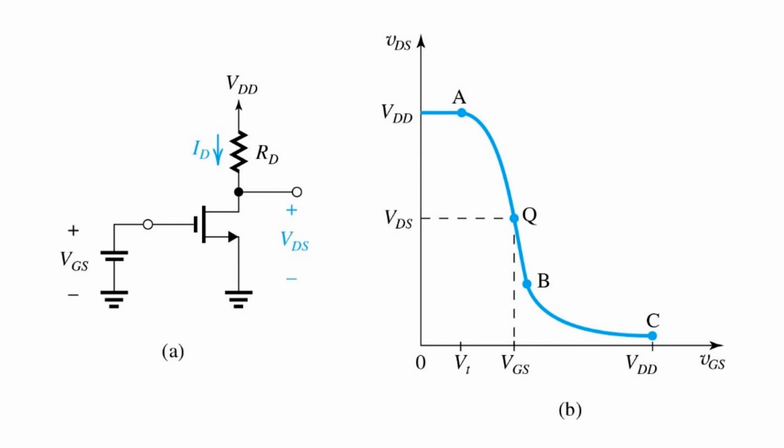Having seen that both the MOSFET and BJT amplifiers are quite similar in form and function, let's return to the NMOS amplifier for our discussion. So again, we saw an input-output relationship like this, and the steep part of the curve arose when the transistor is in saturation.